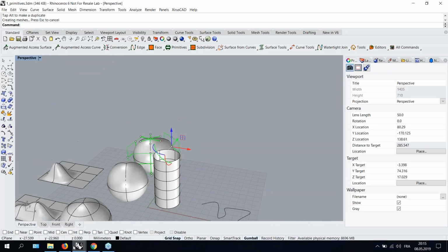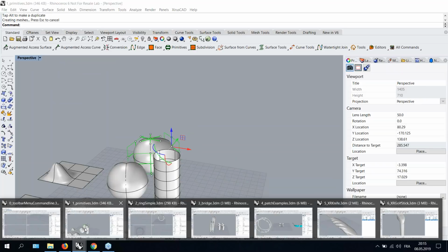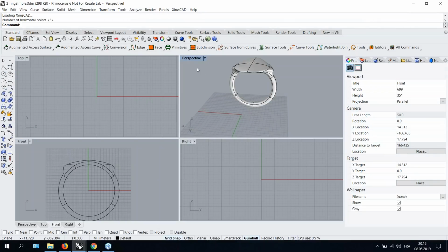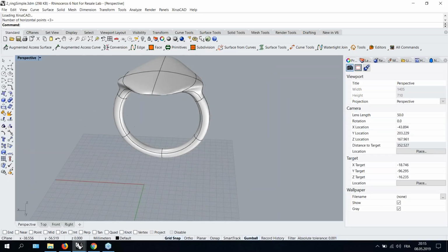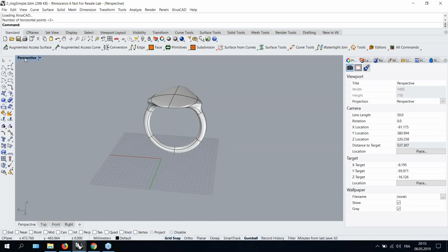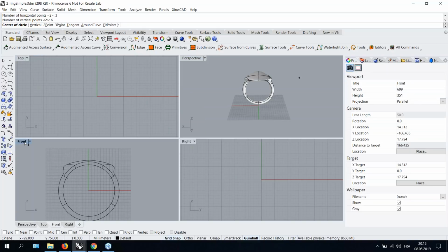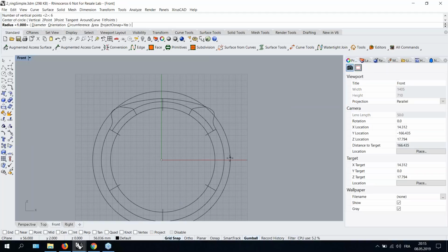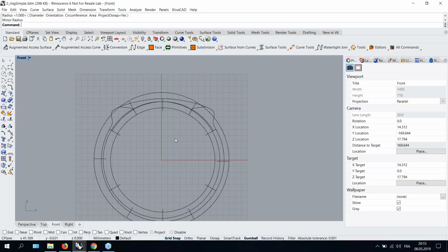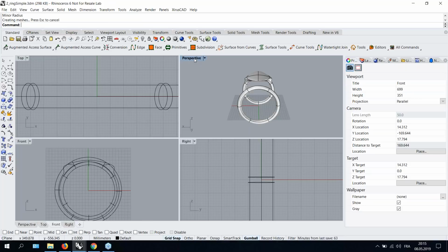Let me go to a more sophisticated example, which is this one here, just to give you an overview of what you can do very quickly with these new Freeform tools. So, for example, here I want to create this structure from a torus. So I go to primitives, I choose torus, and I can specify the number of control points that I want to have in both directions. And then I just quickly draw here the example that I already have drawn before, more or less. So this is very, very quick, as you can see.